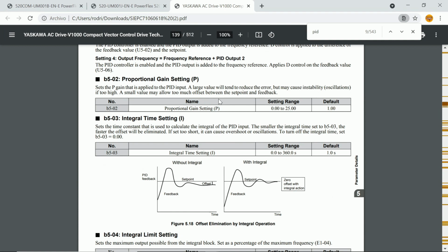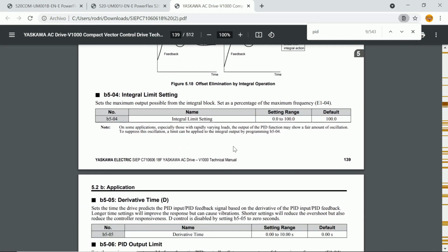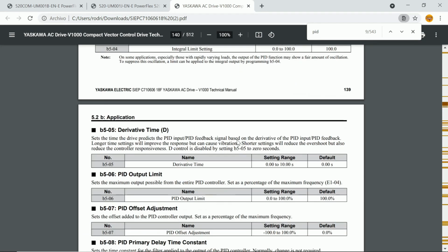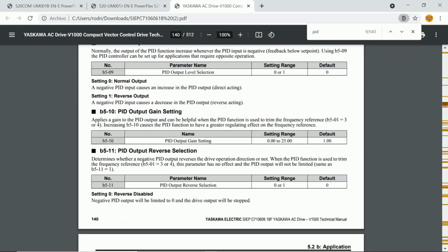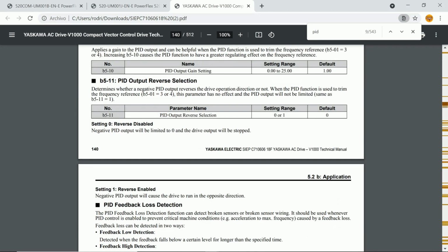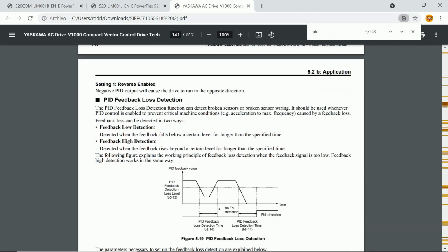If you wish for control aside from the independent tuning for the PID, then you can enter the ranges manually: the proportional gain and the integral time. And how are you going to get this data? As I previously mentioned, through software, or if you want to do it by hand, the calculation is okay to do. But there are already very efficient ways to get our PIDs.